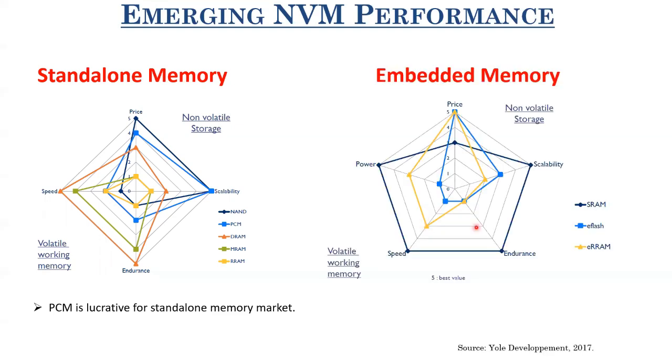So let us take the case of SRAM first. Each individual SRAM cell has 6 transistors, but those transistors are highly scalable. We can use 5 nanometer technology transistors or 7 nanometer technology transistors, or any advanced node transistor, and utilize them for making SRAM. And therefore its potential for scalability is high, although a single cell has 6 transistors. And just because a single cell has 6 transistors, its area is large. And as I told, in VLSI, cost is a function of area raised to power 4, and hence its cost is somewhat higher. Not somewhat higher, it's actually very high.